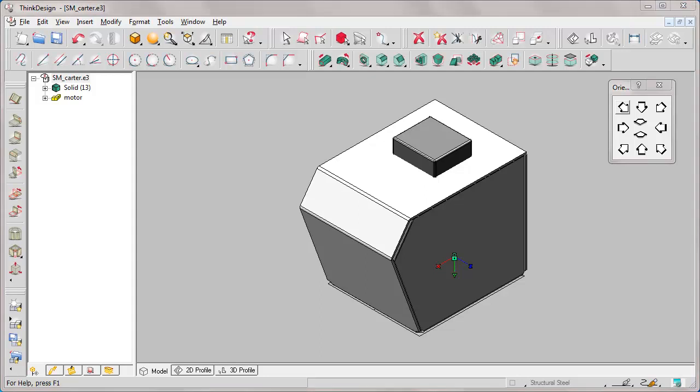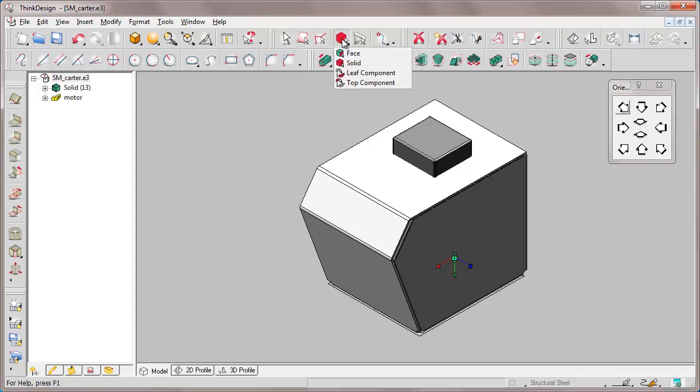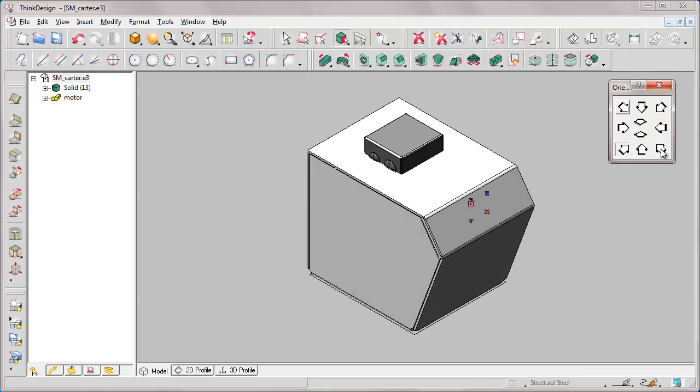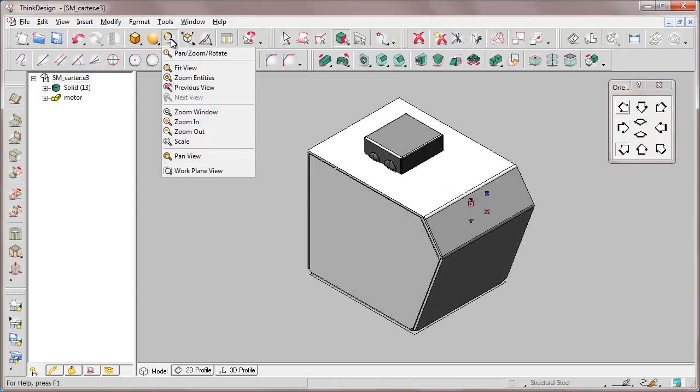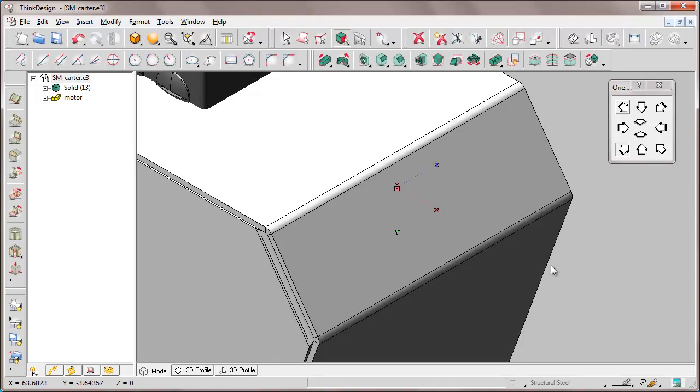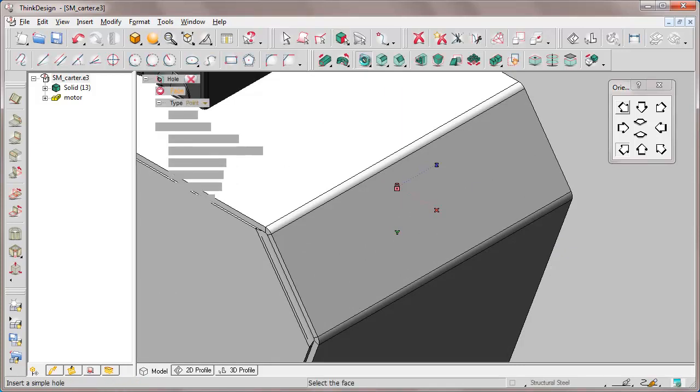Let's go on with our tutorial. Our crankcase, our chassis, is taking shape. We can use both approaches combined, the one for sheet metal processing, that is, sheet metal features for the bending and forming process, and standard solid modeling features. In fact, now we need to add some holes.